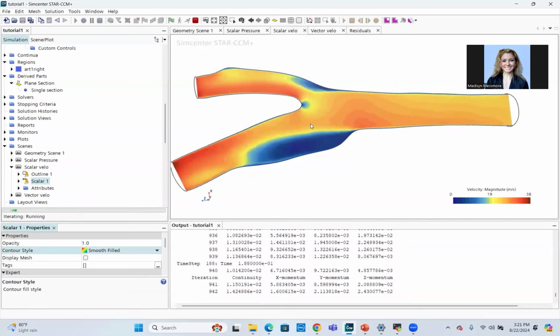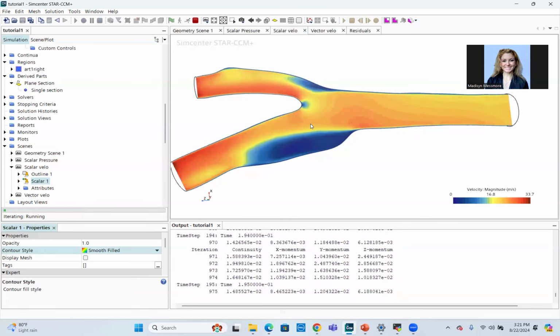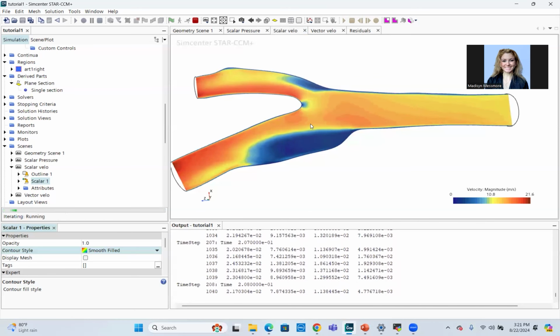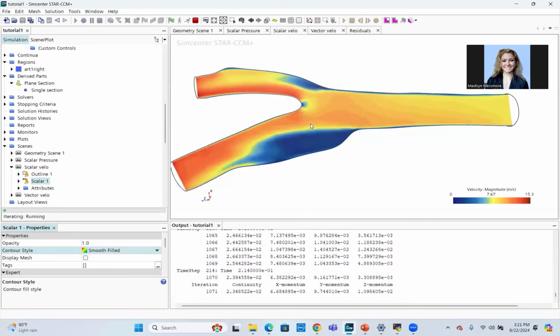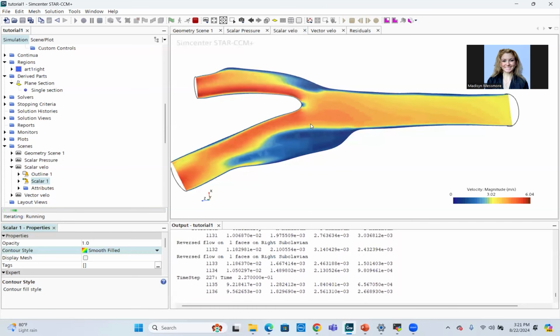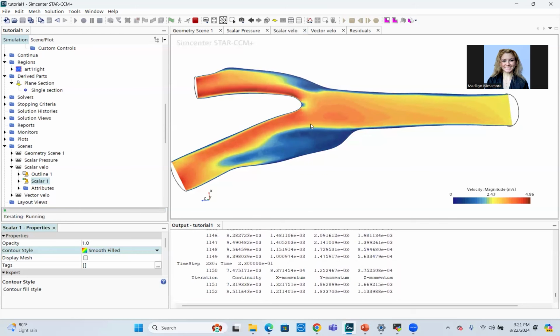They have to branch. Branching is technically not great from a fluid standpoint because, so you see how you have those blue pockets? What's really happening in here and also at that peak here is you're forcing the flow to separate, and when it's being knocked out like this, it comes around, and then in here it's swirling. So you have a low velocity because sometimes it's not fully going forward. It gets stagnant in here. And what happens when you have stagnant blood flow? You get clots.